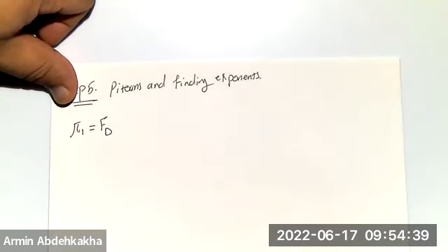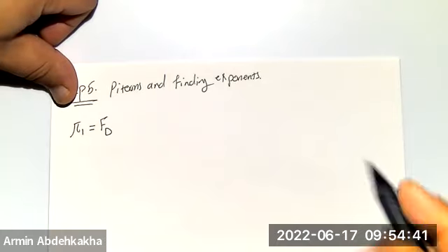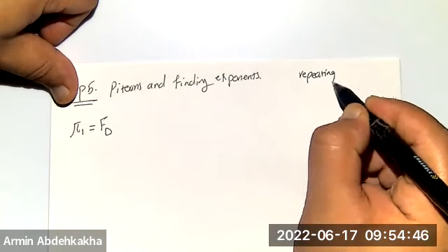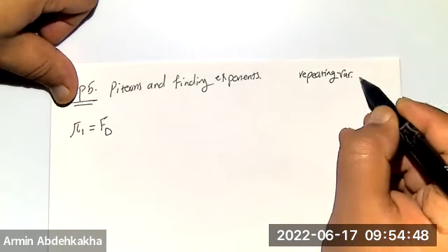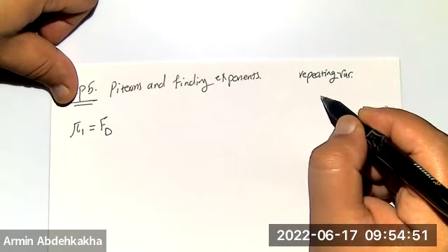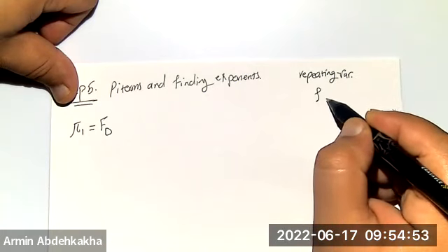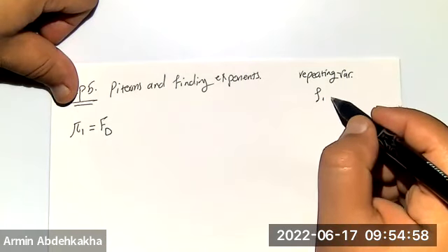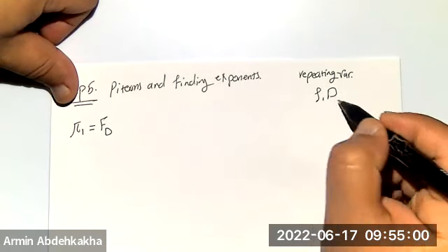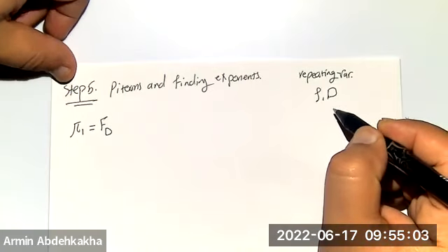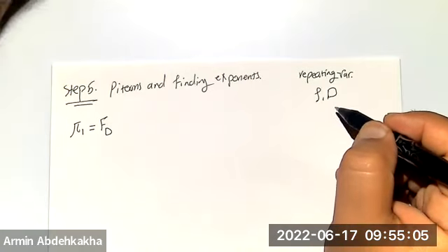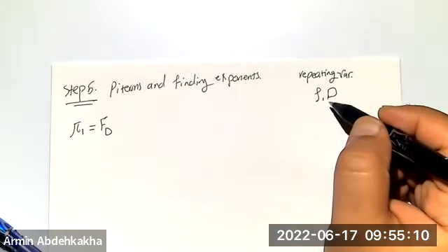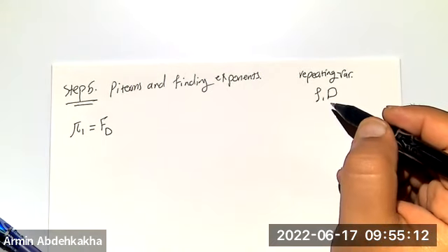Let me write that my repeating variables are rho, chosen between rho and mu, and between the two D's, capital D and lowercase d, I choose the D of the ball because it's much more important than the lowercase d, which is for the dimple depth.